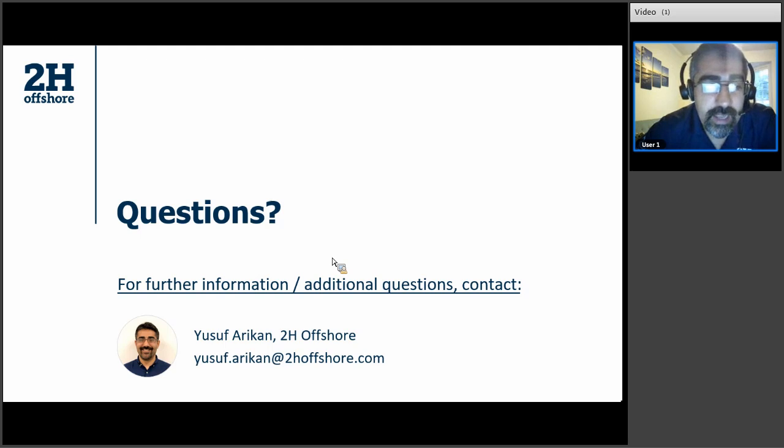So we didn't design an anchor for this study, but it would have to be based on the seabed condition. It would either have to be suction piles or driven or drilled and grouted piles, or alternatively maybe gravity, but usually gravity anchors are more expensive than the other three.